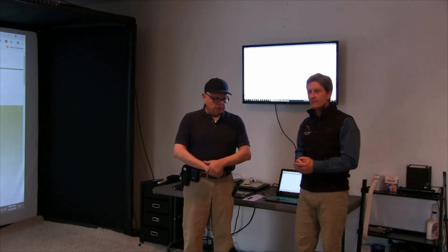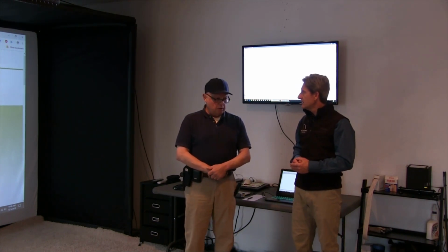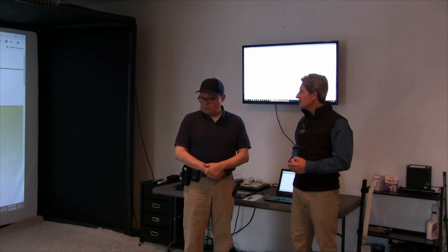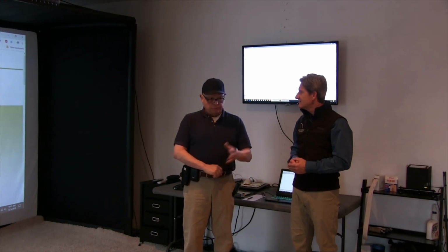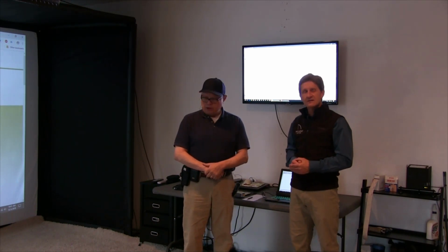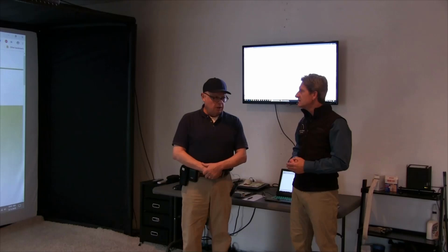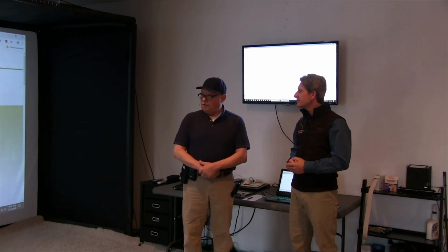The first thing I'm going to do is a quick inspection. I'm going to take a walk around the building, whatever it is that we're measuring, and just get the general lay of the building. As I'm walking around, I'm looking for things like jamb thicknesses on doors and windows. I'm looking for ceiling heights, anything that's a little out of the ordinary.